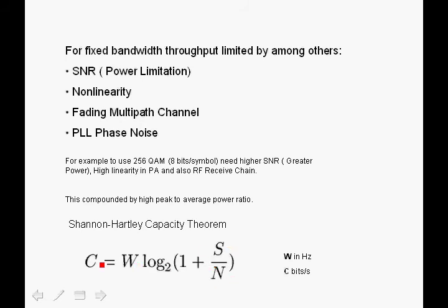One way to increase capacity is to increase the signal to noise ratio, but if you have a bound, a fixed signal to noise ratio, and also a limited bandwidth, then your capacity has an upper limit. By the way, this capacity is the capacity of the channel in which, below this rate, you can achieve arbitrarily lower and lower error rates, close to zero.